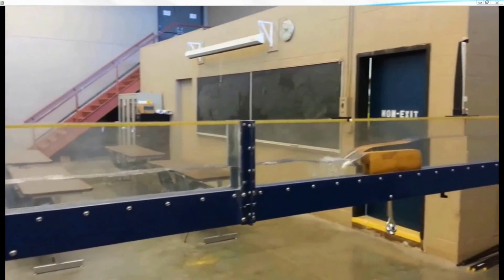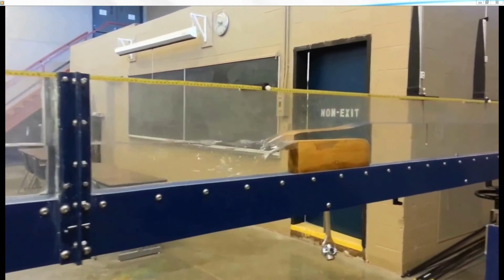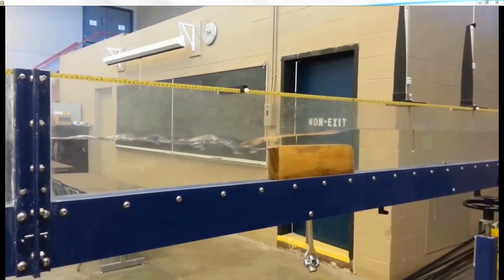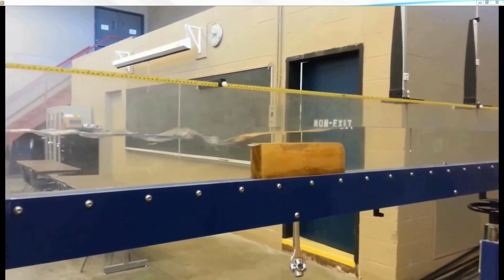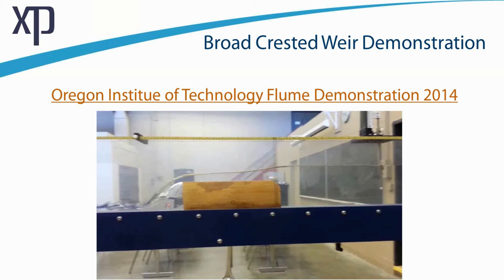Hydraulic models, we usually assess this kind of behaviour in separate ways. The XP products at a technical level typically aren't able to provide some of the detailed hydraulics that we might have seen just at the end there with the waveform. And if you're interested in waveform around particular structures, you would need to consider computational fluid dynamics, which is definitely an advanced component of stormwater assessment.